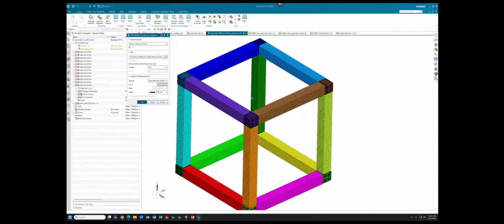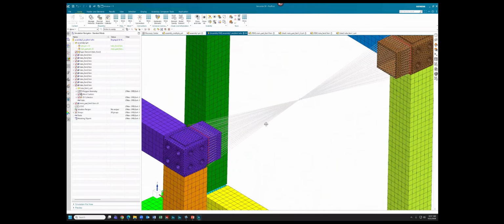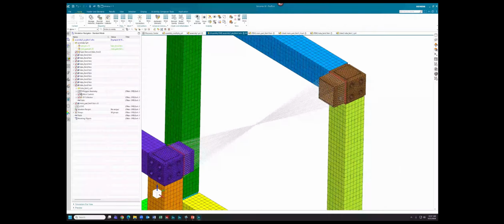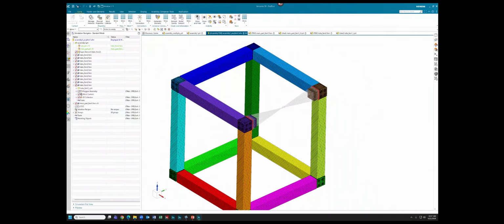Essentially what I did is I solved a super element boundary condition model for this tube. And then I'm able to use the AFEM to connect to that relevant OP2 file. And then it'll actually use that super element representation for your tube, if that's what you want to do. And you can see it has all of my relevant boundary nodes for that super element model. So features like that, really useful.